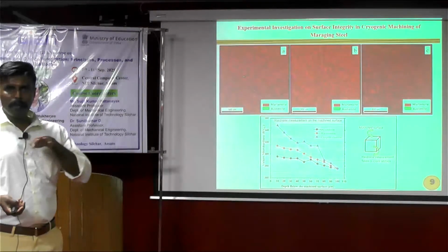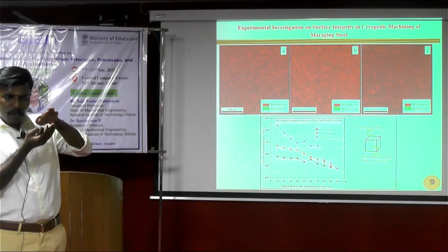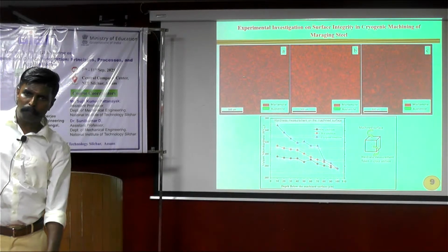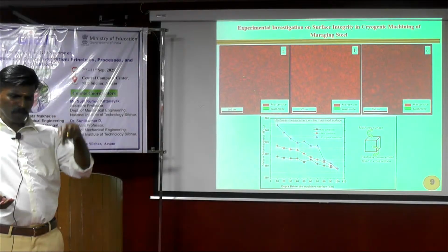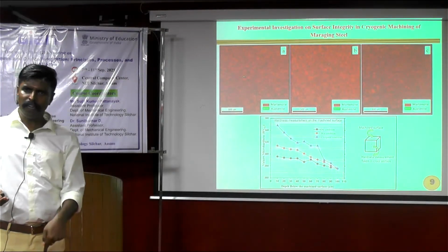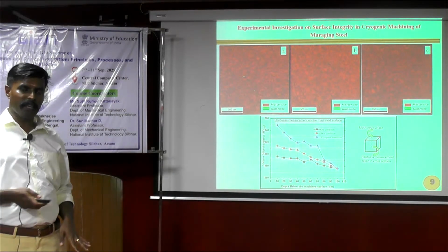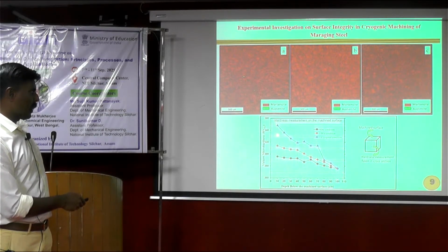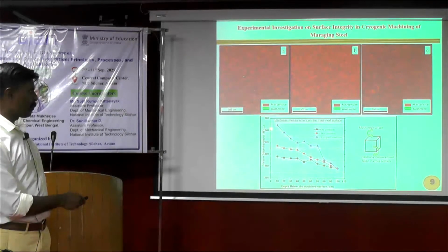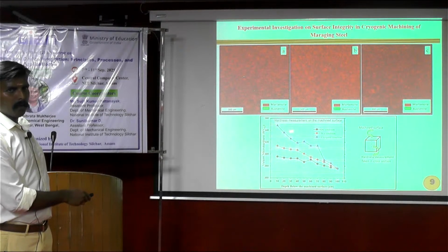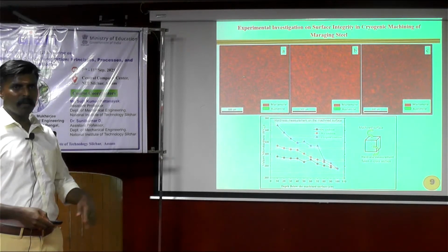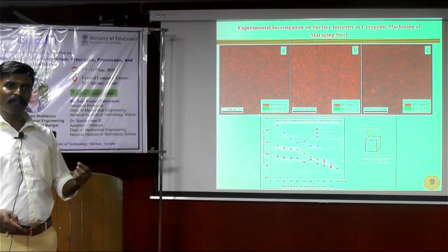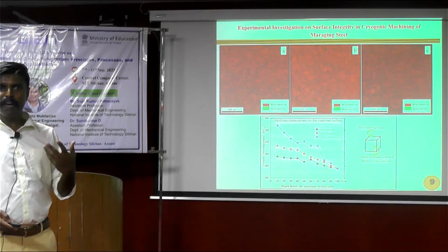If you are doing machining, the top is near the cutting tool, so that material will get more strained. But if you take far away from that cutting region, there the effect will not be much. The same thing here: you see the cryogenic one, that blue color line, near the cutting area the hardness is very high, because of the cryogenic condition we maintained, the microstructure morphology you have seen, and the fraction of grain boundary evolved in it.